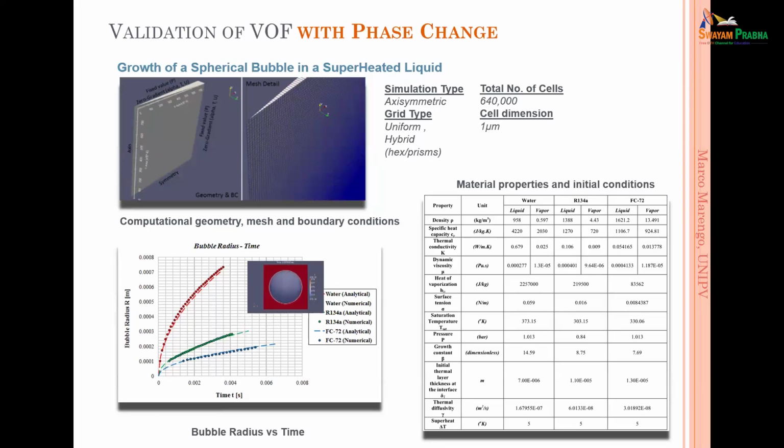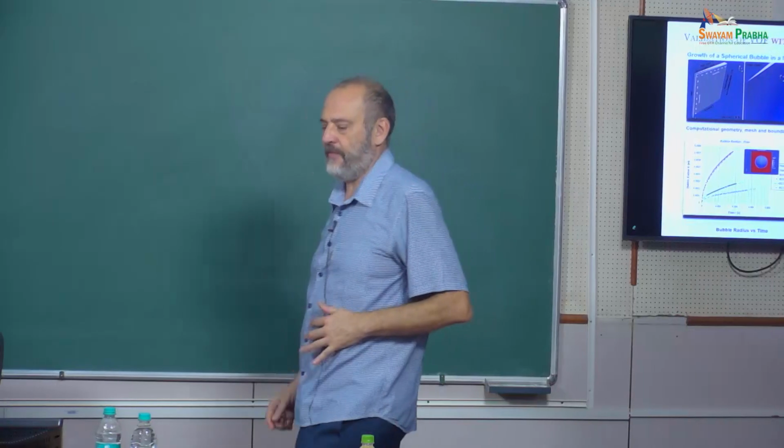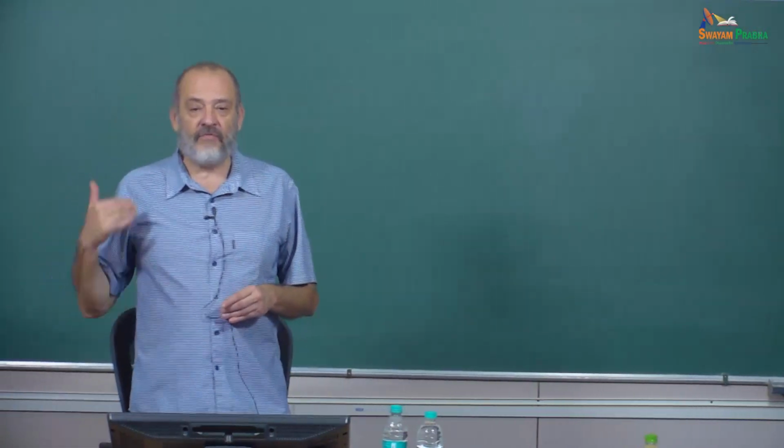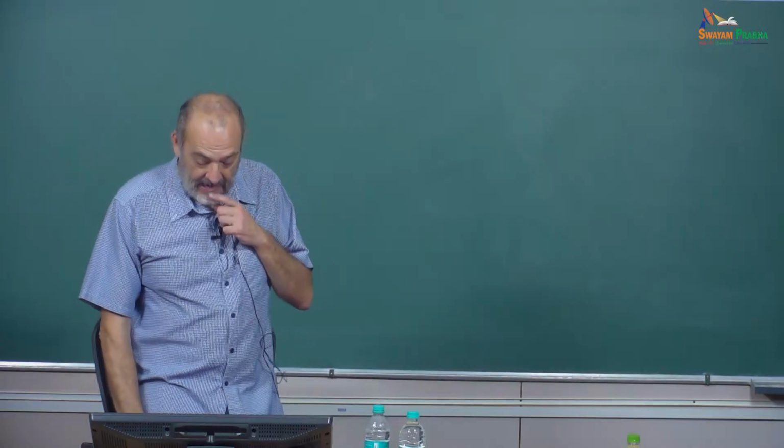So you remember that I have a bigger interface, and we need to have the right position for the mass balance. In this case, if we have only two cells, we are not going to do much. Okay? So we need to allow more cells in order to have a nice estimation of the position. This is the reason why we need to go to 1 micron, 2 micron, 5 micron cells maximum, so the computation is heavy, but it's quite accurate. It's very accurate, yes.